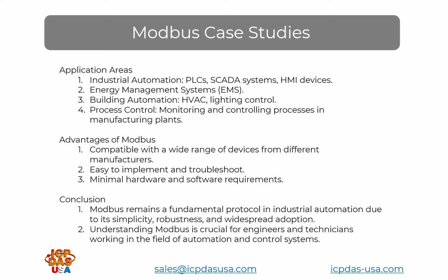Okay, sure. A picture tells a thousand words, so I can find many pictures out there that show daisy chain wiring. We have some in our manuals, but I think we need to simplify some of our documentation as well, because it can get confusing, and I understand how people get confused in wiring, especially when you connect a third-party device, because I noticed that instead of using data plus and data minus, they use A and B, where B is the plus and A is the minus. It's almost counterintuitive to how most people think, where A should be the positive and B should be the negative, but I've seen it be the opposite. So you definitely need to pay attention to that, and biasing could also play a part in it as well.